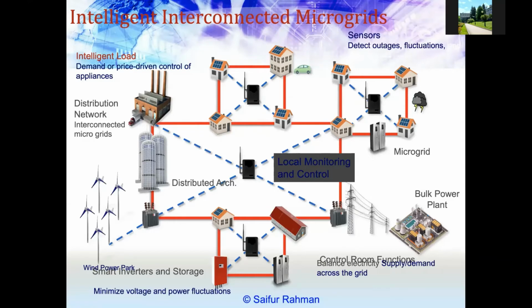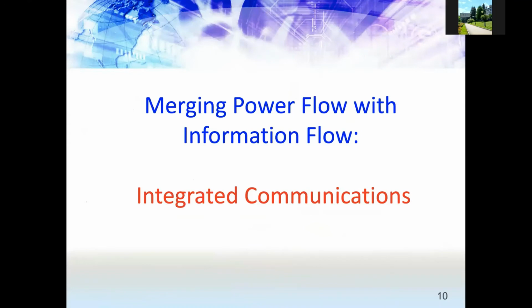So that's what I mean by a component of the network, a microgrid, which can function without the network being available all the time. Again, as I said before, my focus is reliability first. So this is how I can provide more reliability. A transmission line can fail, but you can manage locally quite well.